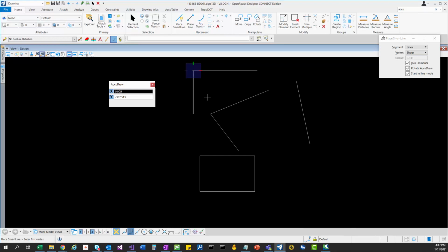So some other things we can do is switch the mode to a polar mode. If I hit the M key for mode, it's going to toggle me to polar mode, and now I can key in a distance and direction. Just like the X and Y keys to lock X and Y, I can use the D key to lock the distance. I hit the D, you see how my distance is locked. And I can hit the A key to lock or unlock it for the angle. I come here and I hit A and I lock the angle, right?